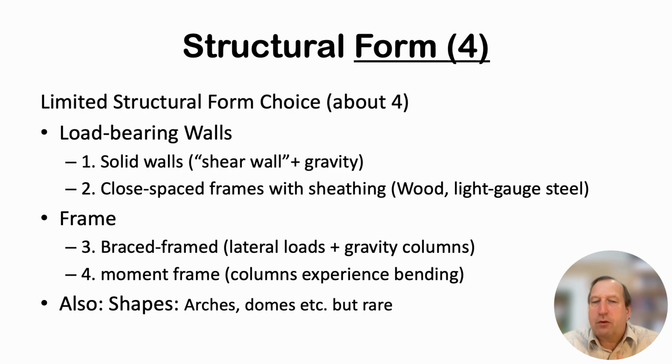The use of closely spaced members like wood studs or light gauge steel studs, when combined with some sort of structural sheathing or bracing, form the equivalent of a wall. So they're not nearly as strong, but they behave in very much the same way as if it were a concrete wall or a masonry wall. It's just that they are much more lightweight and weaker.